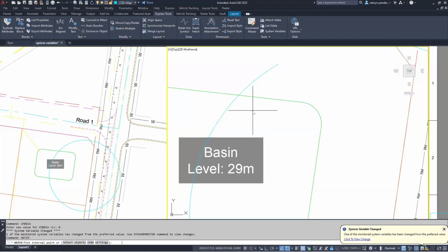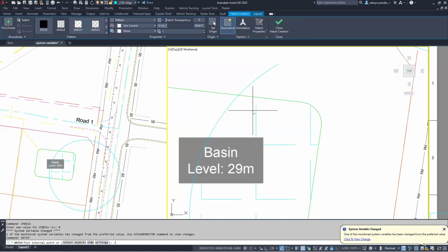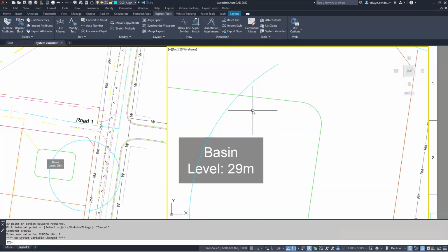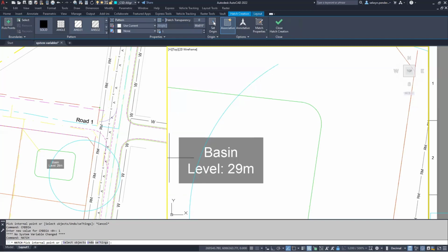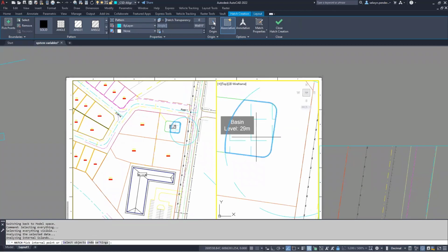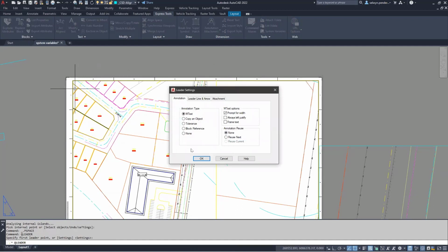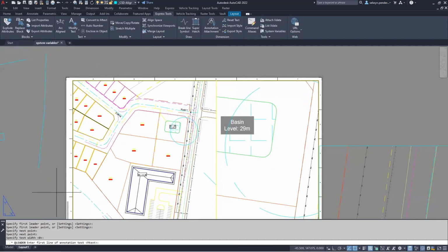Okay. Yeah, normally hatch would come up with a dialog box. And with CMDDIA set to 0, the dialog box won't appear. If I set it to 1, type hatch once more, we'll now have that dialog box, I hope, somewhere. Hold on. Okay, certain commands, dim edit, qleader, they have dialog boxes. I'm just going to do qleader. Okay, that will do.